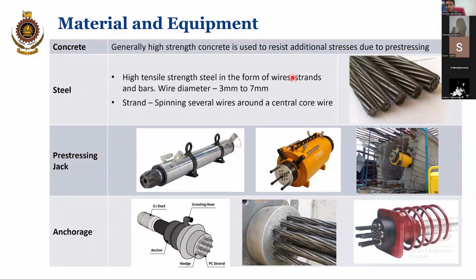And a lot of the segmental box girder type ones are post-tensioned, because you insert segment by segment leaving ducts, and the strands that you insert actually help to hold these segments together. Once you apply the post-tensioning, it places and holds these in one position, acting like the bond between different segments as well. So that is another benefit of using post-tensioned segmental box girder type bridges.